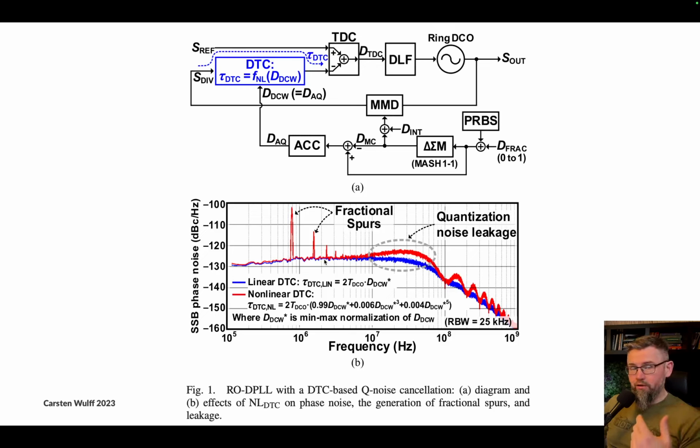For example, for radio, you need relatively low noise. But for Bluetooth, it's not that horrendous noise requirements. But for LTE, then it becomes more horrendous. So the type of PLL and how much current it's going to use is really dependent on what you're going to use it for.